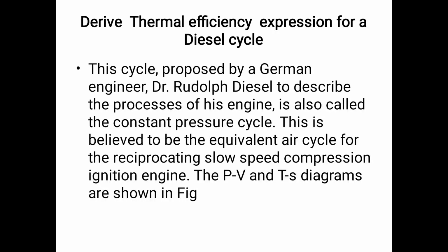Diesel cycle. This cycle, proposed by a German engineer, Dr. Rudolf Diesel, to describe the process of his engine, is also called the constant pressure cycle. This is believed to be the equivalent air cycle for the reciprocating slow speed compression ignition engine. The PV and TS diagrams are shown in the figure.